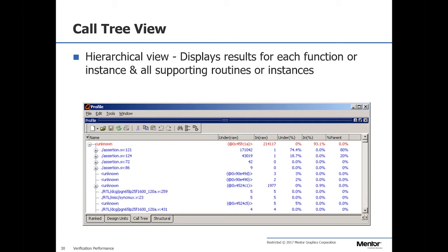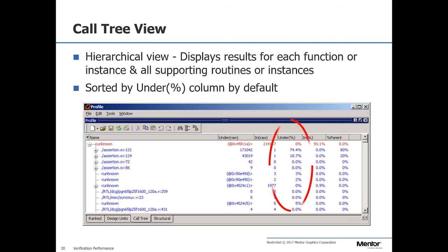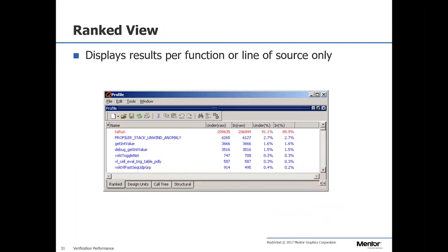30 times faster. If I do that for these two, this is what you hope to find if you have that situation where you're saying, damn, for some reason this is running like 4 times longer than it used to, is that you screwed something up, you added some code, and you set up the sensitivity lists incorrectly so that this code is firing off all the time. If you fix those two things, you'll probably see a huge jump in your simulation performance. That's the kind of thing that you hope to see in your profiler. So that's just one of the other views, the ranked view.